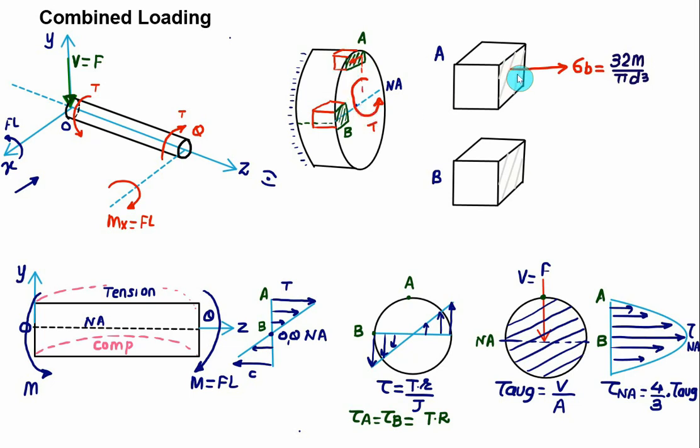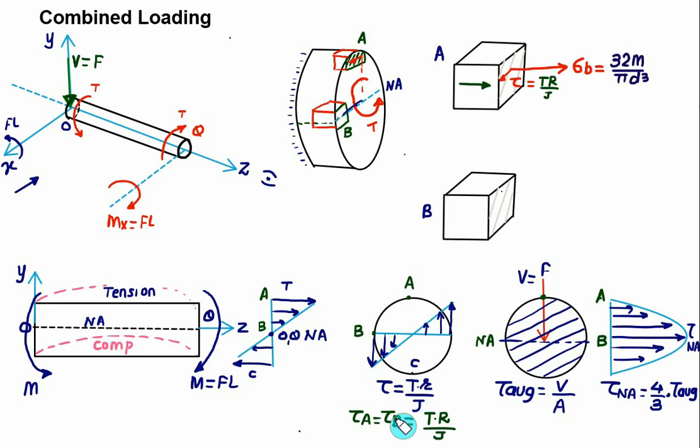So on this face I have to show one shear stress. This one is a shear stress tau, and this shear stress is due to the torsion. The shear stress at point B, which is on the outer fiber, is a maximum value, given as T into capital R divided by J. So one by one you have to complete all the three figures on face A. Already we have shown the bending stress that equals 32 M by pi d cube.